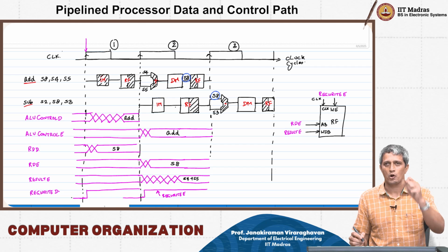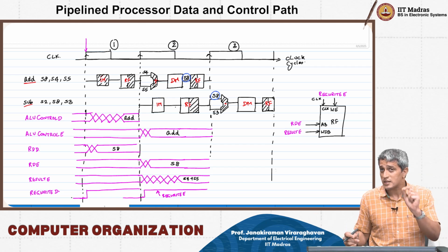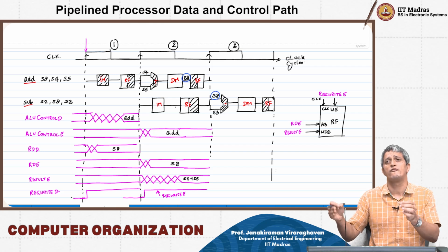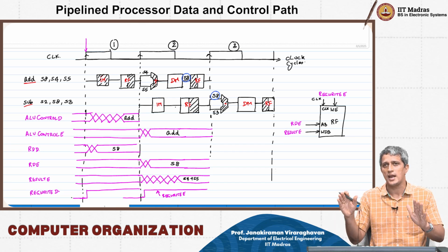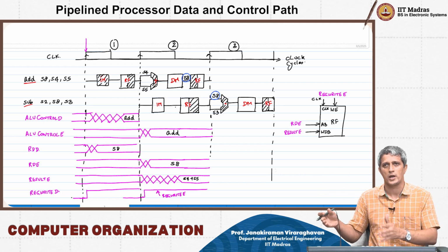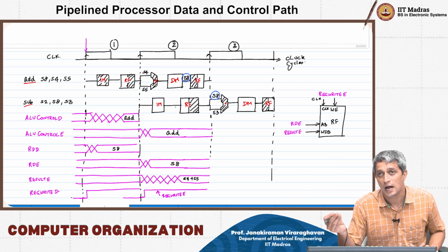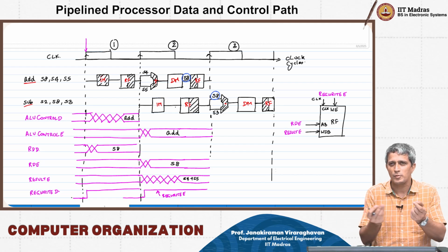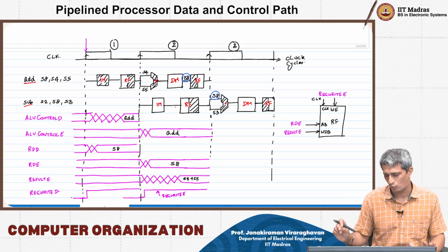This is what is controlling every flip-flop, register file, everything in the system. And we are assuming that the exact same clock goes to every single node in the system, and therefore there is no delay. So all these edges go up together, and therefore everything is expected to happen, at least ideally, together. In reality, there will be a small delay, skew and all will be there, but ideally we do not want that.